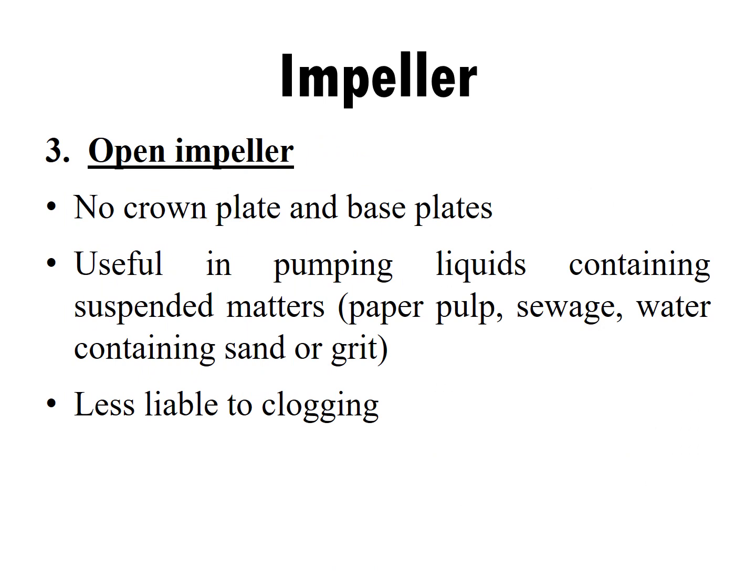Now open impeller means there is no crown plate and no base plate. It is used for pumping contaminated water or water which has suspended matter like paper pulp, sewage, etc. And it is less liable to clogging because it doesn't have any restrictions or coverings.